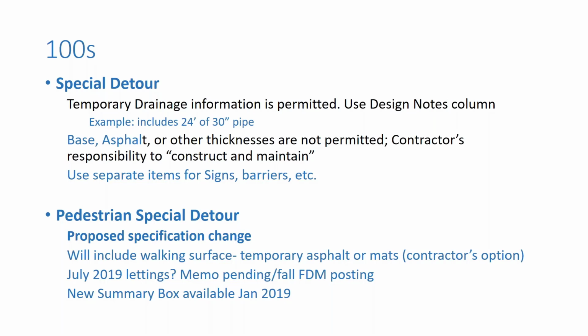However, remember that base or asphalt or other thicknesses are not permitted in the special detour information, as it is the contractor's responsibility to construct and maintain the special detour. We also use separate items for signs, barriers, and other pay items. So please do not include those in your special detour quantity.